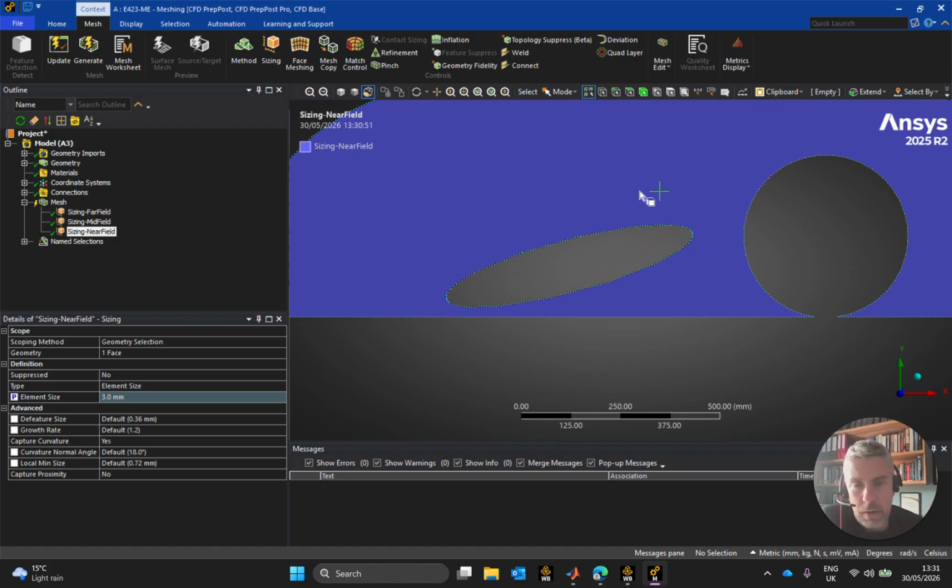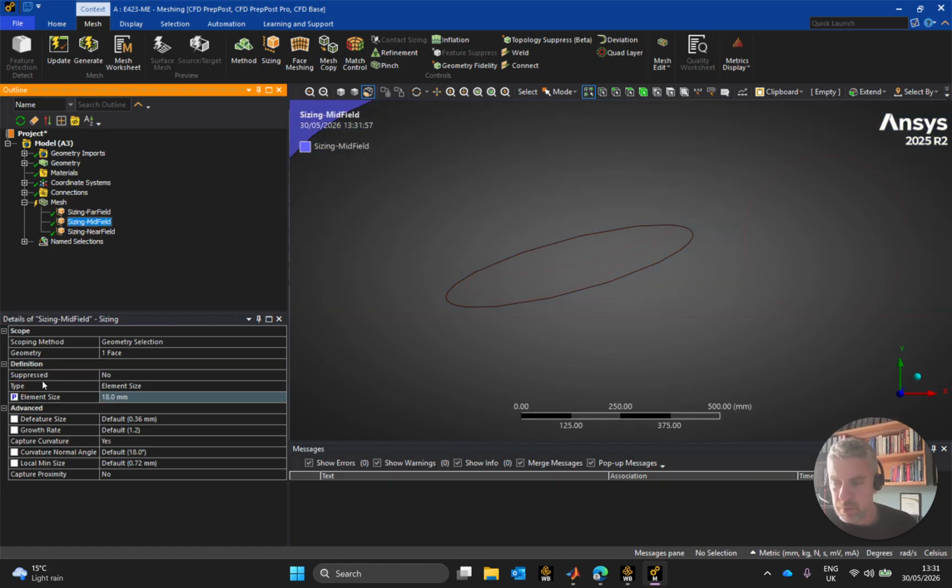Whereas if they're small, I might get a brand new mesh, because I will be making small increments of maybe half degrees. Then when I come in to remesh it, I want to make sure that a new mesh is generated in places where mesh elements are being put where there is no mesh. If they're too big, the software might just squeeze the mesh elements a wee bit. So I want to make that very well resolved there, 3 mil, and I'll try it at 3 mil and see how we go.